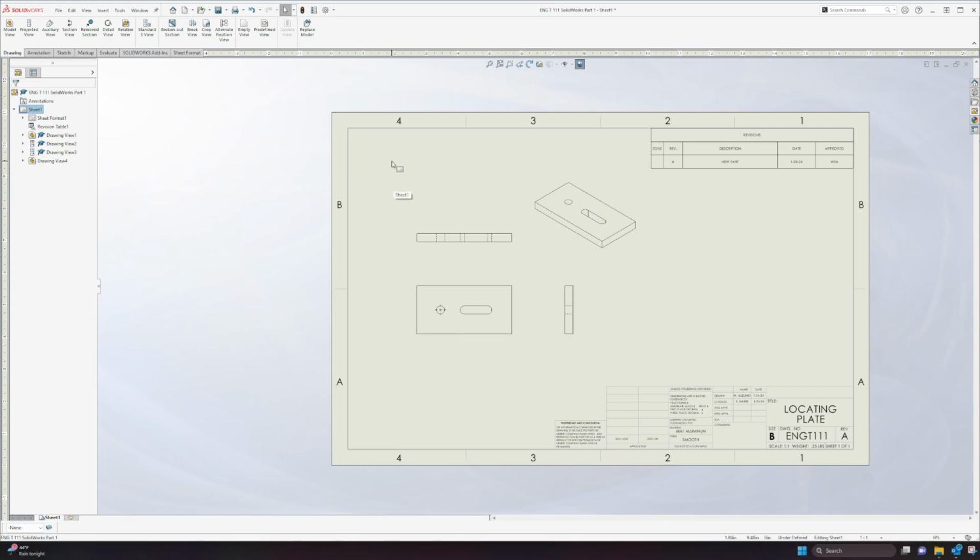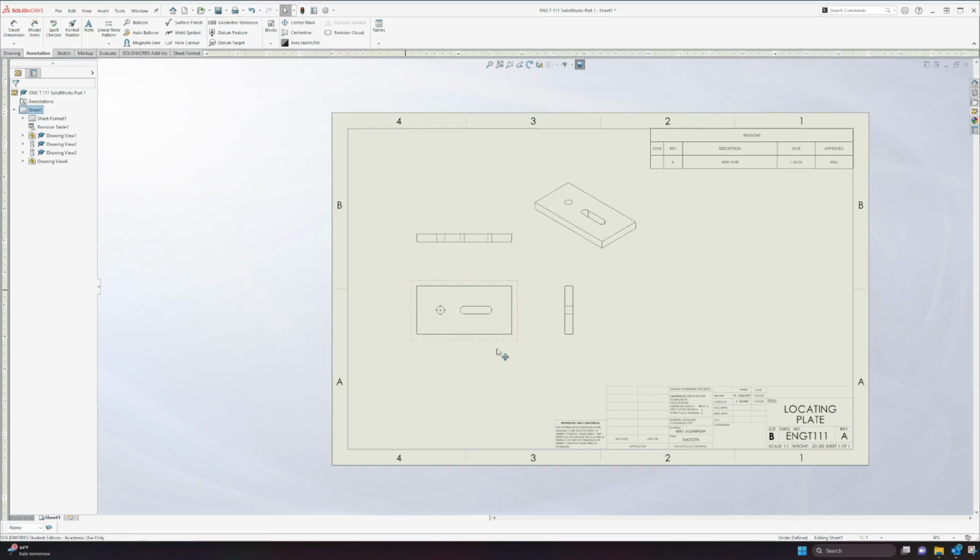Now, much like when you're creating the part, there's a similar tool there in Sketch or in Annotations, here in the Annotation and Sketch tab on your command managers. There's a tool here called Smart Dimensioning. You can find that again in Annotations or in Sketch. It's the same tool that you would use when you apply dimensions in a Sketch environment when modeling this view.